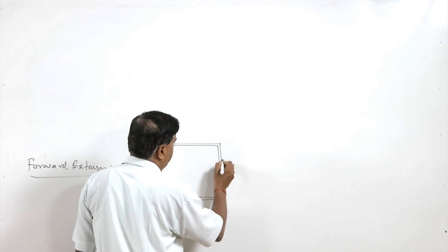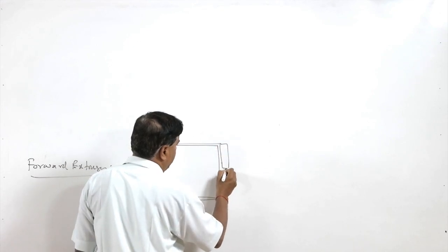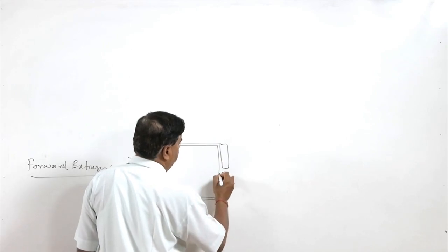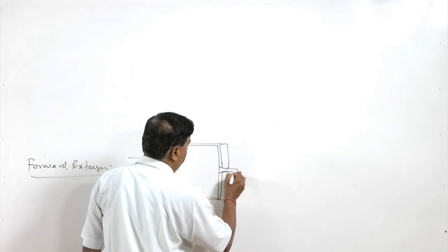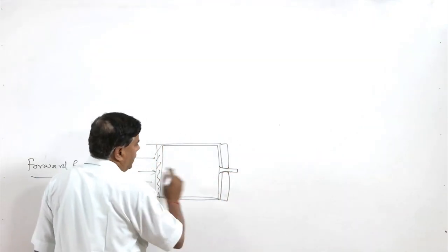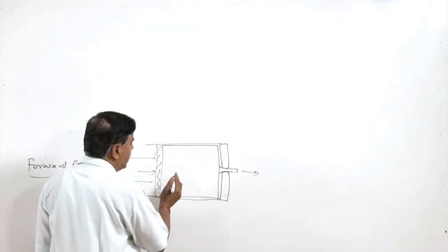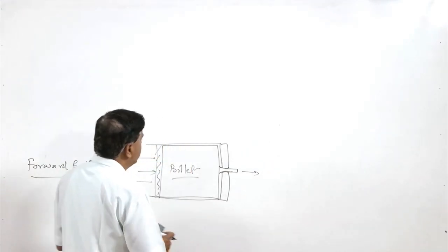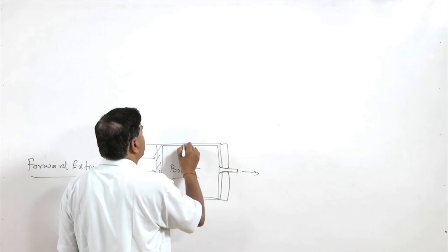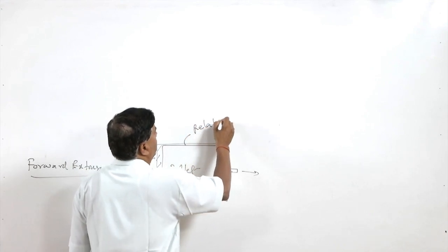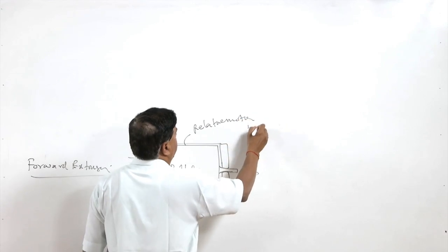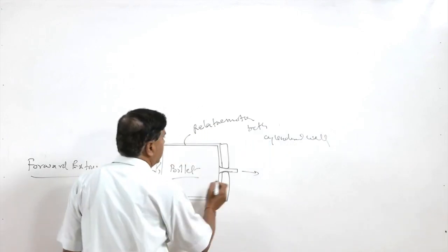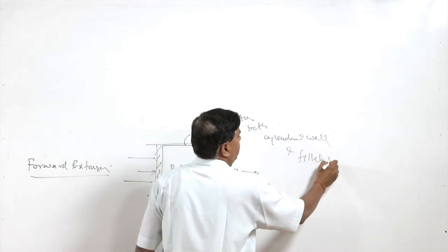Then metal starts flowing out of the die and takes the shape of the opening of the die when it flows. As the metal flows out of the die, gradually the metal of the billet is consumed, and in this process there is always a relative motion between the cylindrical wall and the billet surface.